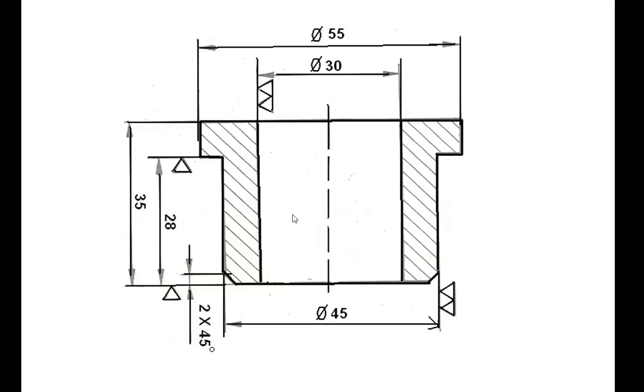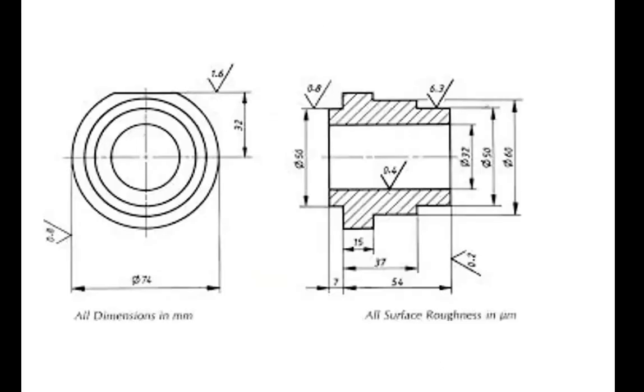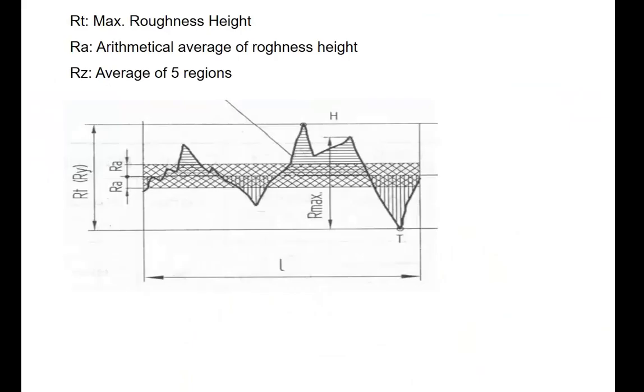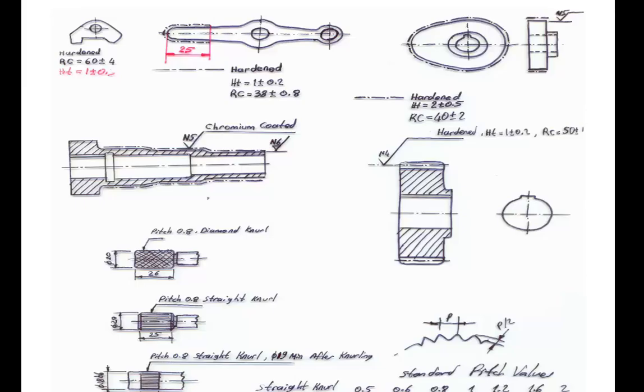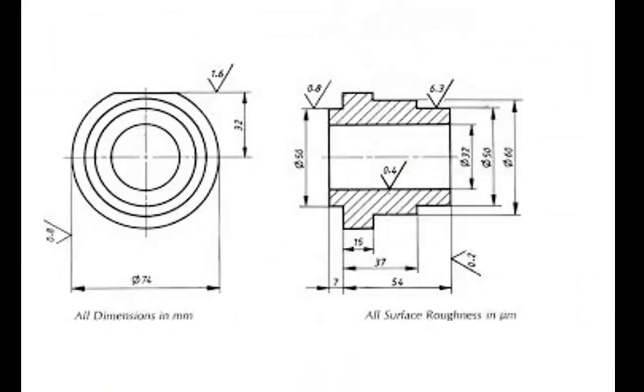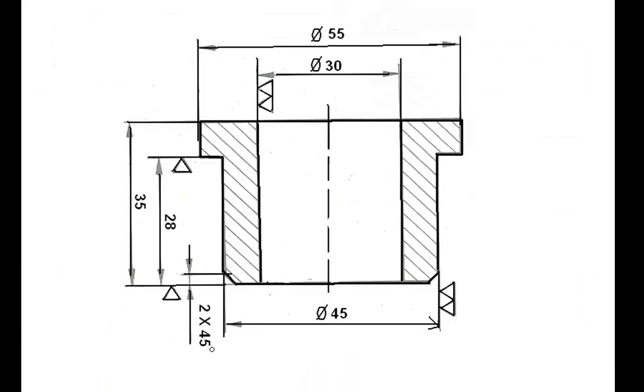If the surface is to be kept to its existing quality, no finishing process is needed, then show the surface with a tilde. Well, actually there is no such symbol in this example, but say that over the surface we have a tilde.